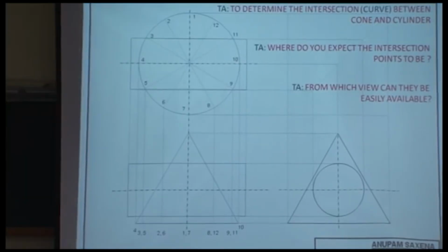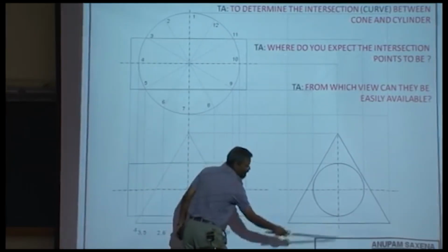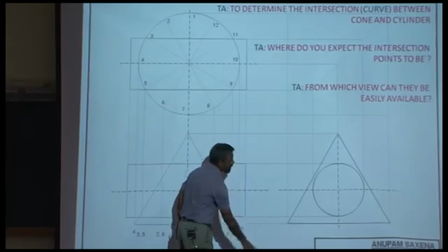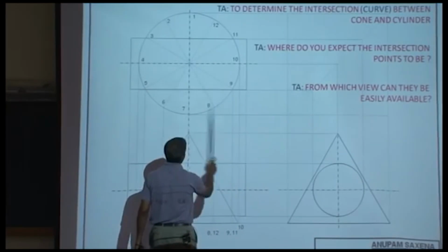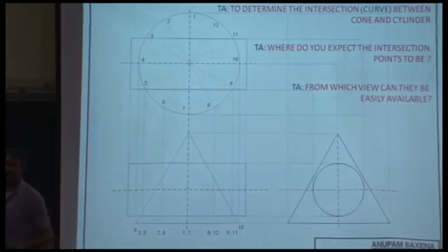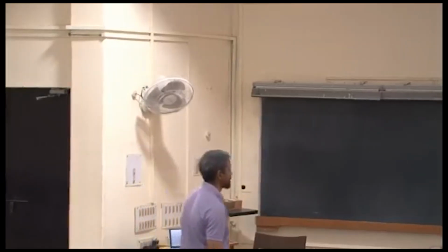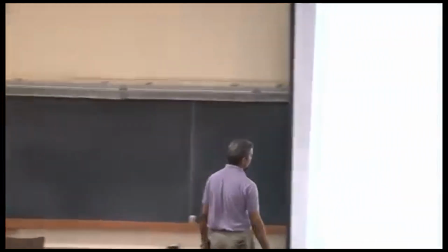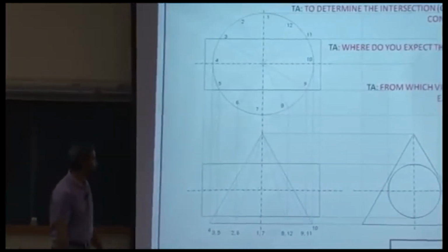All right. Now, I'll do the same exercise. I'll represent these points onto the base of the cone in the profile view, and for that I'm going to be using this 45-degree line. So essentially I'm going to be taking these projections and transferring them onto the profile view. The reason why I said the numbering is going to be very important is because here you would note that the numbering will change. Of course, when I do that, I'm going to be joining the apex of this cone to all these points on the base of the cone. Same thing.